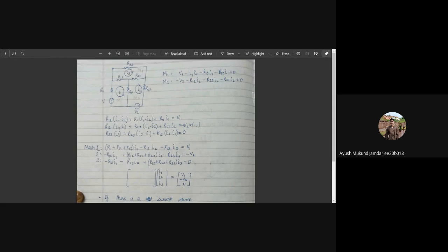And in the last video, we just discussed nodal analysis and its implementation using Kirchhoff's current law. This is a continuation of the same video. That is, here we'll be discussing loop analysis. Loop analysis is fundamentally based on Kirchhoff's voltage law. That is, energy is neither destroyed nor created when you go through a closed loop in an electrical circuit. And let's see how it can be applied to our circuit.